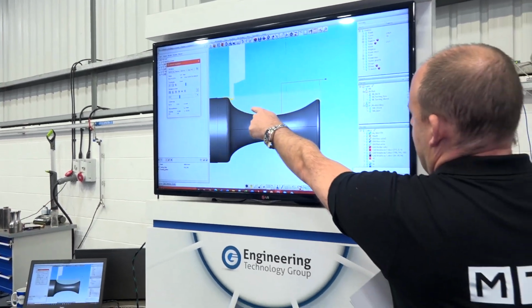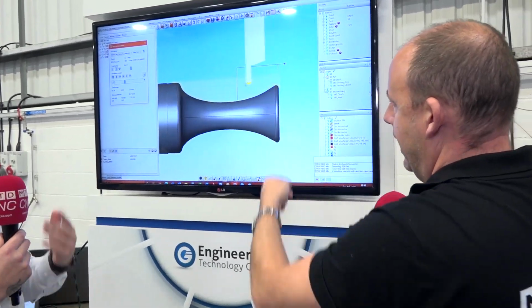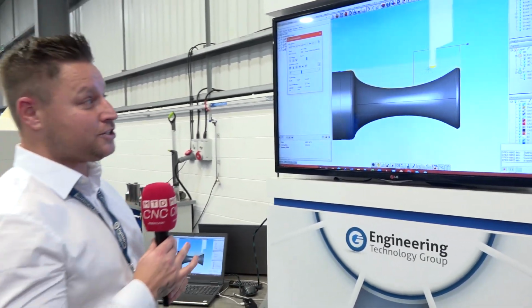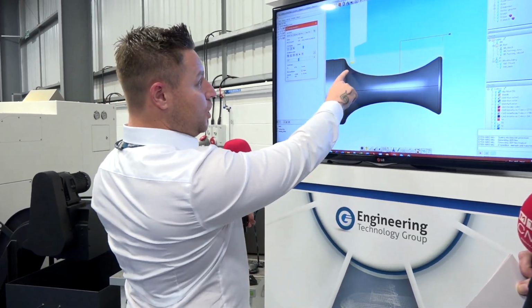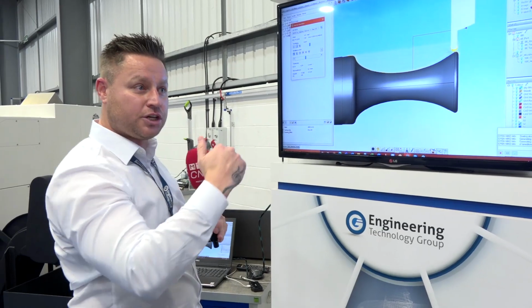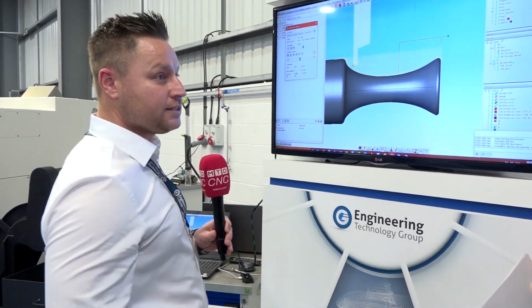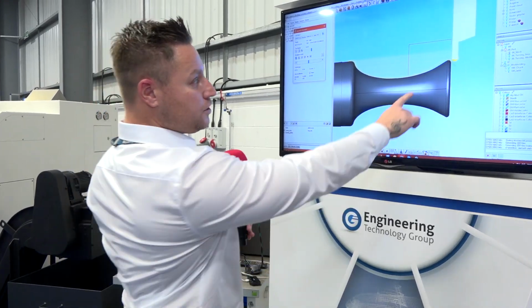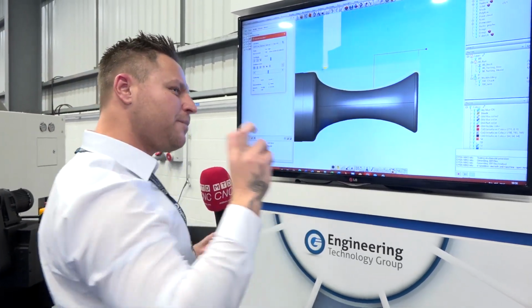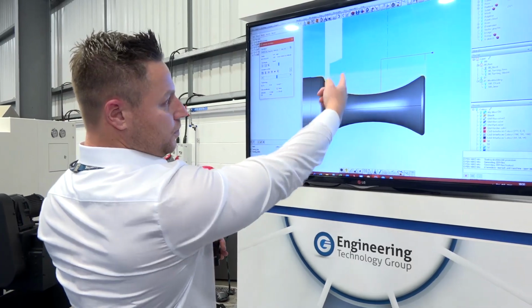What's this indicator in yellow on the button there? That is what we call the cutting point in turning. So when you simulate, you know exactly where your cutting point is, where you set it on the Q setter. You set it on the front face and on the bottom of the radius. If I were using the back end, say on the sub spindle, then that point will be on the back.